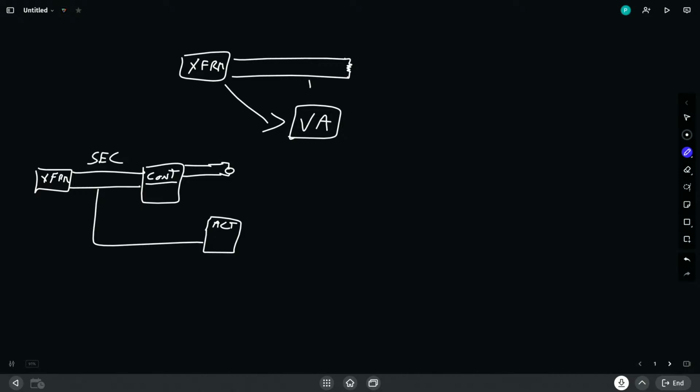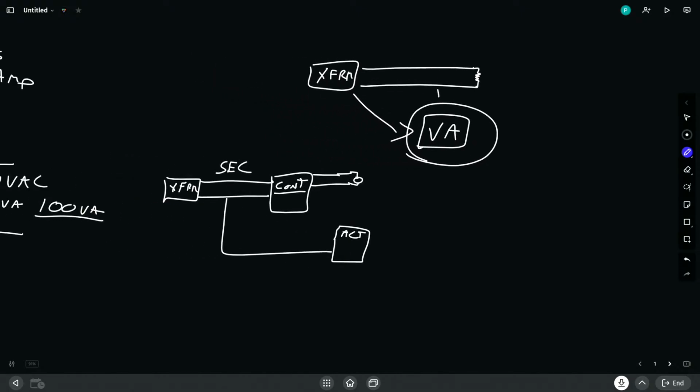Well, that's the same concept of a transformer and decreasing VA. As you put more resistive loads onto that circuit, we are going to see a decrease in power ability to the point where devices cannot fully actuate, or in a worst case scenario, controllers actually start to go online and offline. That's why sizing your transformers for an accurate VA loading is critically important.